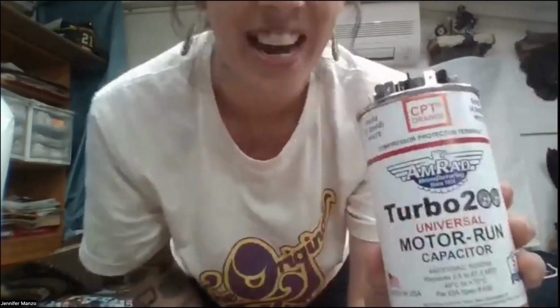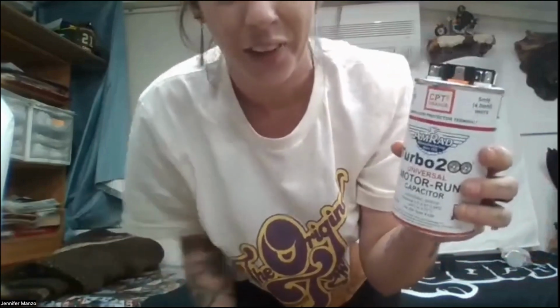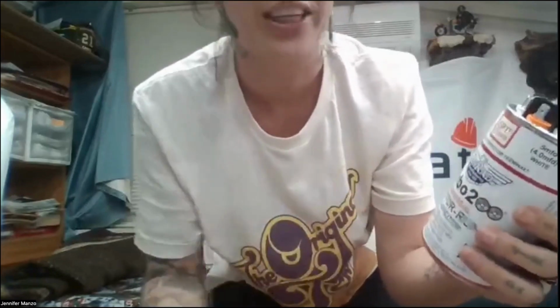This is cool. I absolutely love Global, the source, you guys. The Turbo 200 capacitor. You can wire it 10 different ways. It can be wired as 5 microfarads, 10, 20, or 25. How expensive is that baby? They're actually not expensive. I actually use them for my universals now on my trucks because you never know what capacitor they're going to need. This one does literally 10 different things, and you just wire it according to the color.